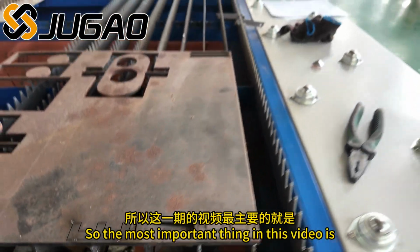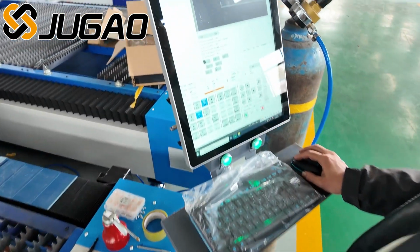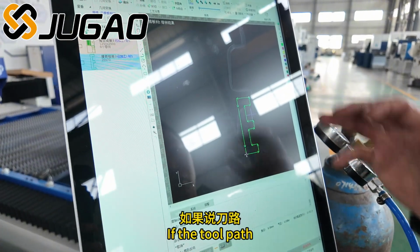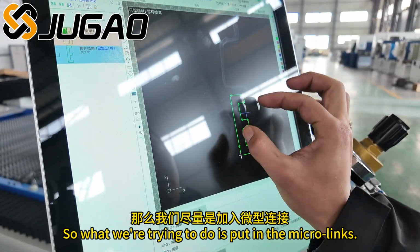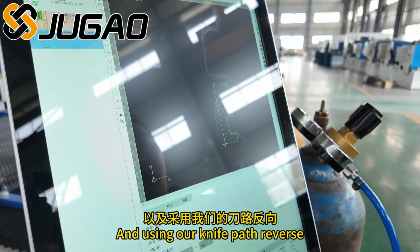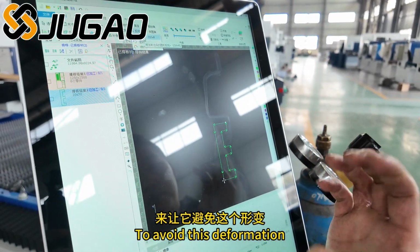So the most important thing in this video is the first thing: to confirm the toolpath. The toolpath will affect the deformation. So what we're trying to do is put in the micro connections and use toolpath reverse to avoid this deformation.